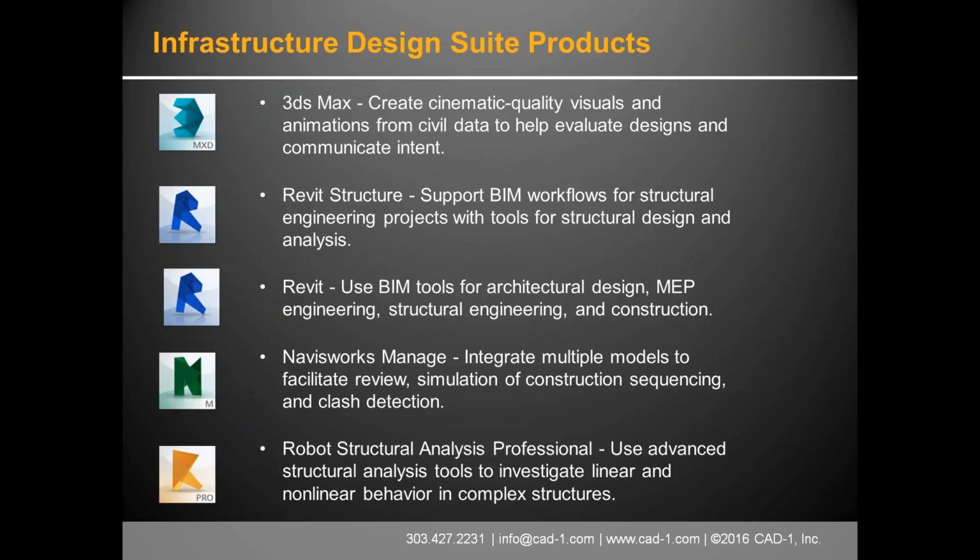And then Robot Structural Analysis, and this is the professional version. Brian, this may be a good one for you too, because I know this is a recently added item. What would be a good reason why someone would utilize this structural analysis tool? So Revit Structure doesn't do analysis. Revit Structure does the modeling. So Revit Structure will go in and model a wall as a load-bearing wall. Robot Structural Analysis will then figure out, okay, what are the loads on this wall? What are the loads on the weld that takes the beam into the column? That's what the structural analysis piece does.